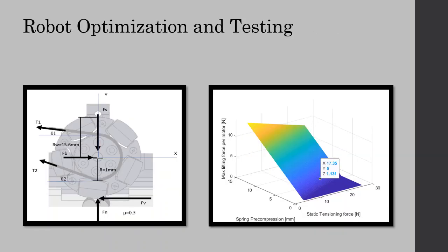The force of the vert wheels normal to the paper is critical to the functionality of the device. If the normal force is too high, then the device might have issues with the first sheet fed. If the normal force is too low, then the device would lift less weight than it's capable of. The vert wheel system was designed in a way that allows for tuning of the normal force by changing the tension in the belt. Through testing of the device, we decided on having a low normal force applied to the lower two vert wheels. This allows for reliability necessary for competition.